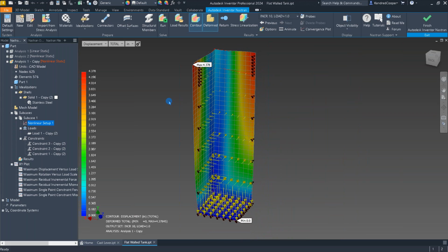It's still a good amount, but I don't know that I would qualify that as a lot across 8 inches. I would expect that flat wall tank to have some movement, to have some flex. 4 inches, yeah, maybe, depends on the situation. You're going to know based on your products, your designs, and your criteria, whether this is good or bad. It's all going to be relative.